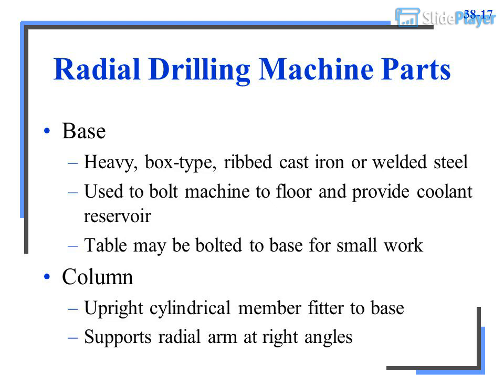The head houses the change gears and controls for the spindle speeds and feeds. The drill spindle may be raised or lowered manually by means of the spindle feed handles. When the spindle feed handles are brought together, automatic feed is provided to the drill spindle.